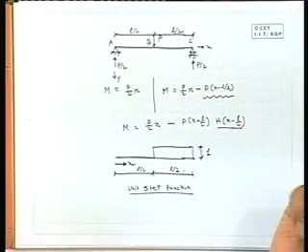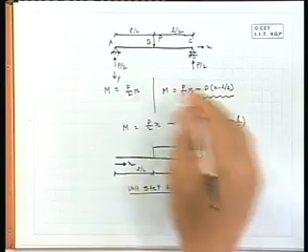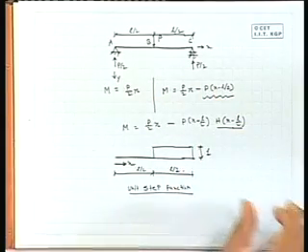Right. Now, this is a simple case with a load P, but there might be another load here. So, there should be one segment, two segments, three segments. The first is P by 2 into x, the second part is P by 2 into x minus P into x minus L by 2, and there should be a third segment, so this plus something. A number of unit step functions may be there, not only x minus L by 2 but might be x minus say 3L by 4 or something, where the load appears on the span of the beam.